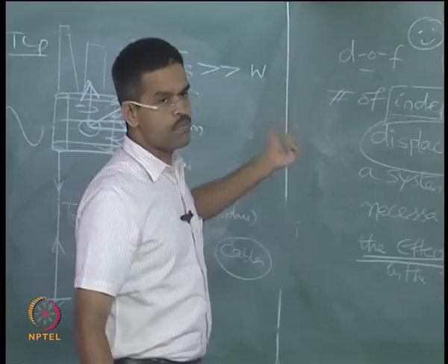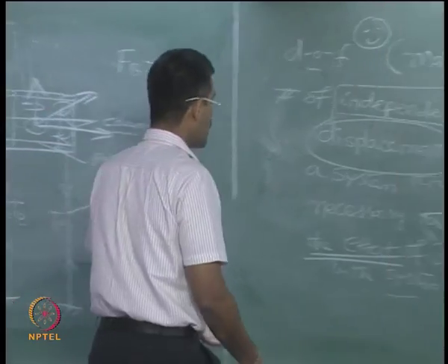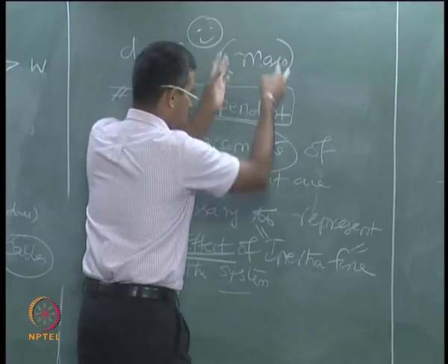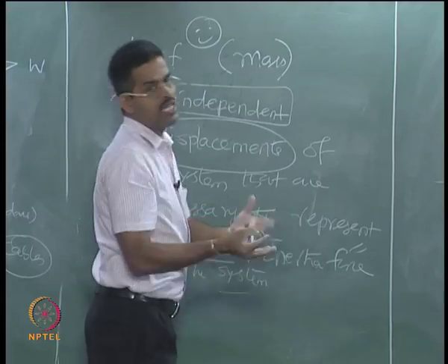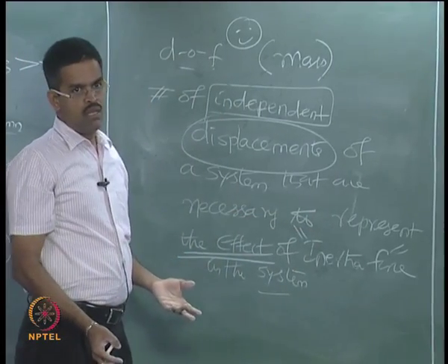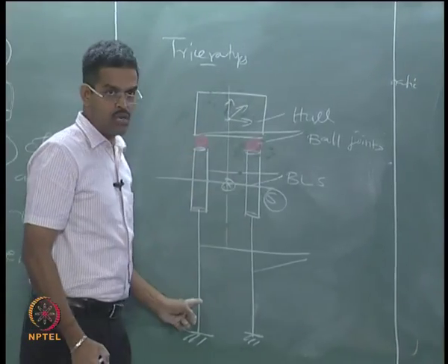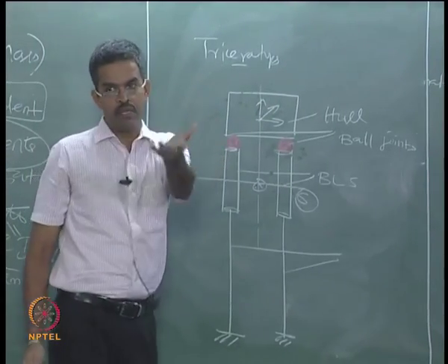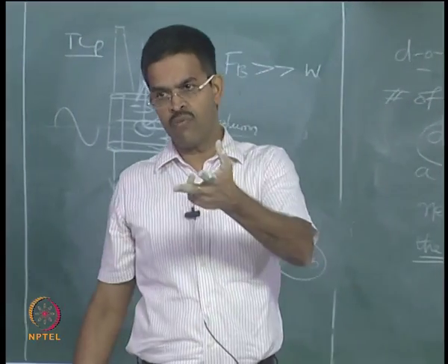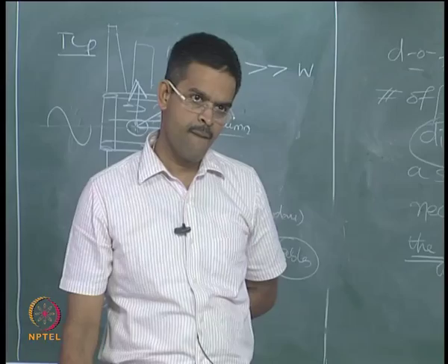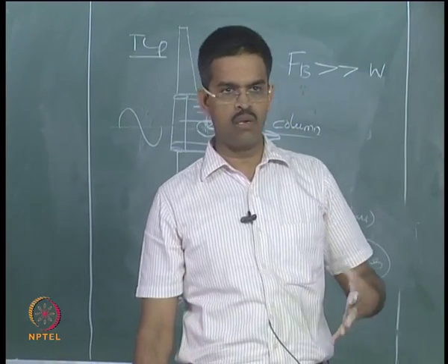So, degree of freedom explains all these complexities in a very simple statement, saying that look at the independent displacements where mass is lumped, look also for the significant contribution of inertia at these points. So, there is no point in doing all these exercises if your material does not predominantly show an inertia force. Now, the question comes, why we talk about inertia force in dynamics? Why importance of inertia is predominantly high?